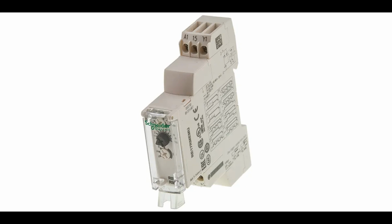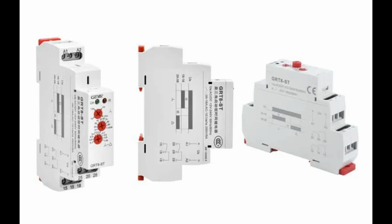Off delay, delay on break. Off-delay relays introduce a delay between the deactivation of the control input and the switching off of the relay contacts, thereby de-energizing the load. After the control input is removed, there is a delay before the relay's contacts revert to their initial state, usually closed to open, deactivating the load.